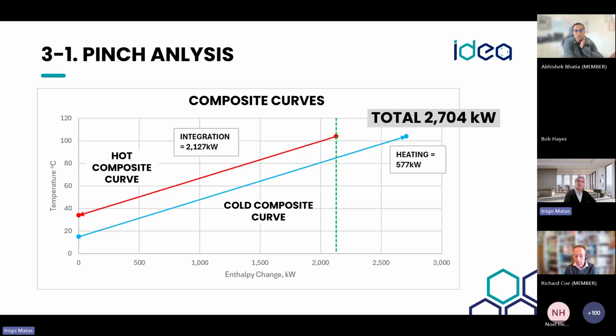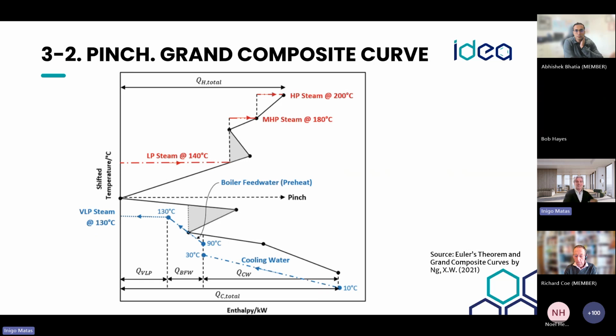Okay, so this will be more on the reduce part. Today we're focusing more on the heat pumps. Sorry, I just wanted to touch on one moment on this part. Traditionally, when we have spoken of energy, we have always looked at energy like steam coming off the boiler, maybe looking too much in detail at the temperature of that energy, which is a very important thing. The level of exergy of a steam at 200 is much higher, it can produce much more work than a steam at 120. In the past, we used it without maybe looking with too much care at what was the temperature available. So that is something the pinch can give us as well.